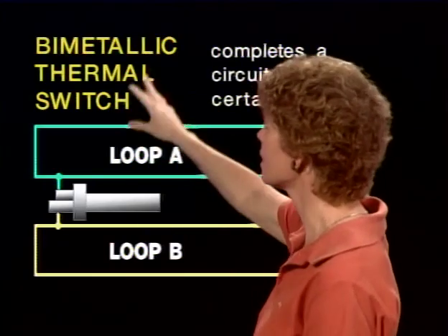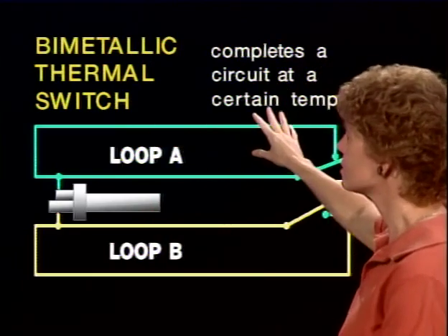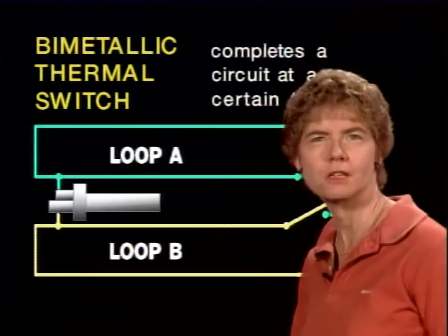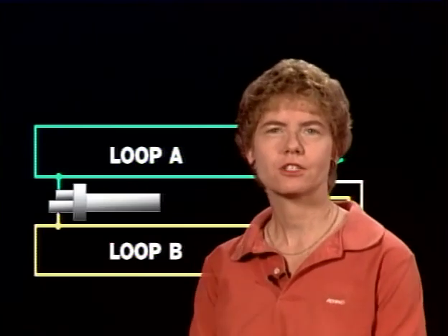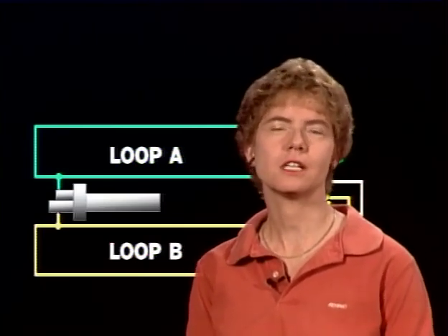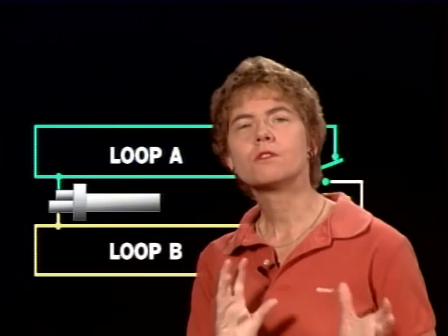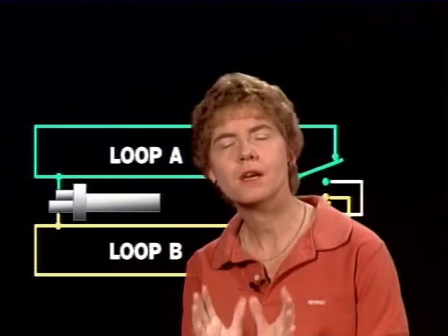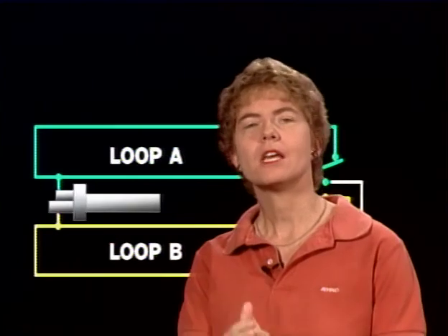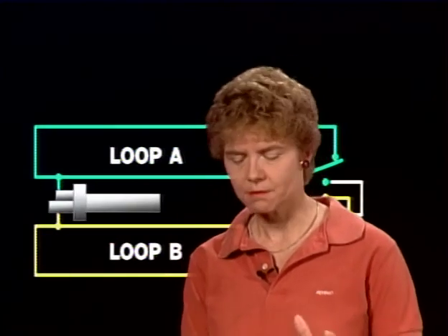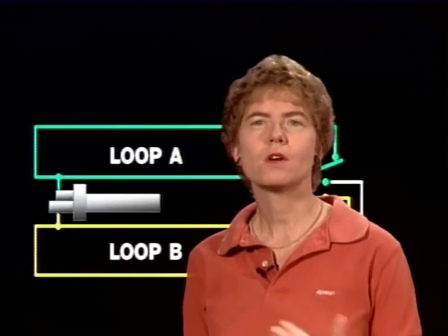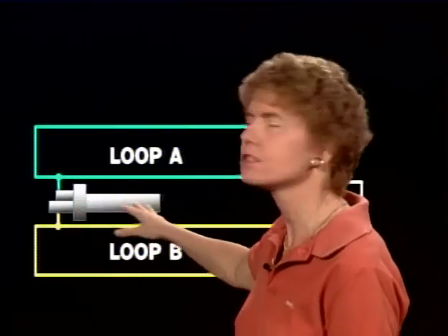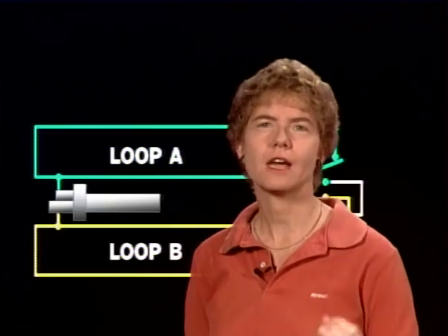Thermal switches that are used in a fire detection system that has a single indicator light will be wired in parallel with each other, but in series with the light, so that any one of the switches that does sense a fire can turn on that indicator light.